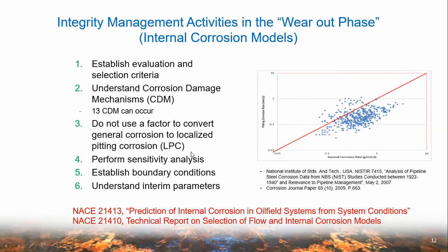Whatever you do, please do not use a model that converts general corrosion rate to localized pitting corrosion. Science and large amounts of field data collected over 75 years have clearly indicated, as given in this diagram, that there is absolutely no correlation between general and pitting corrosion rate. Note that this plot is a log-log plot.